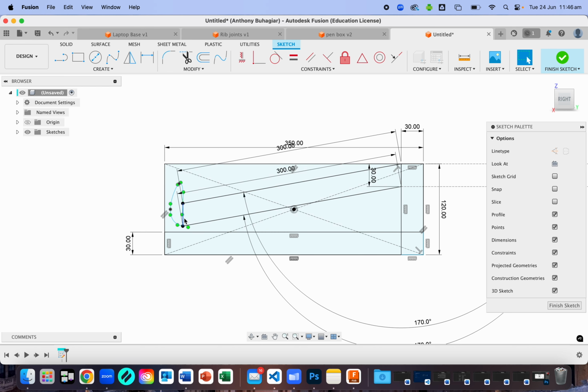So you can drag from the little dots that are on that spline to adjust its thickness, to adjust the curved nature of the spline, and if you then click on the black circles or the black dots, you can adjust the height and the depth of it too.